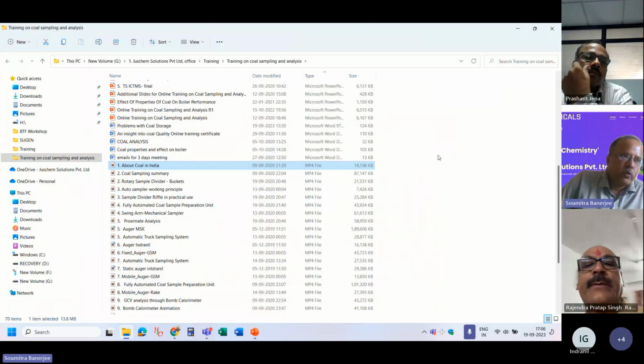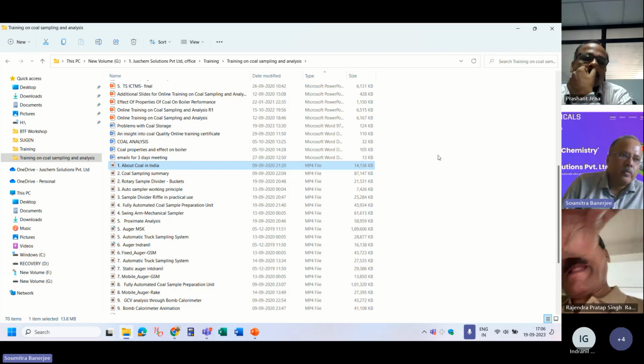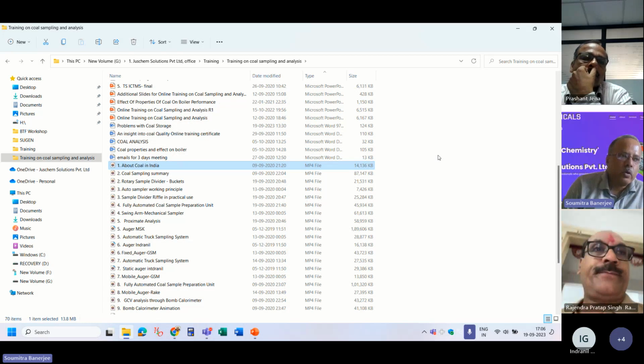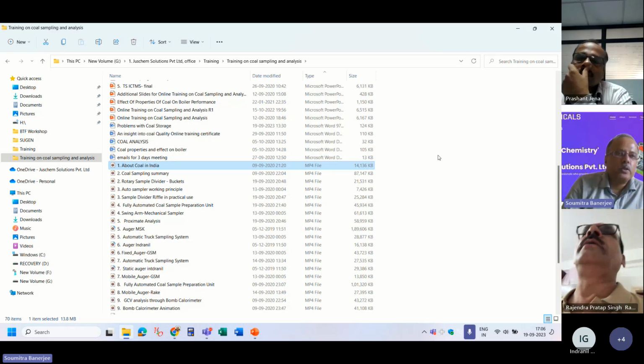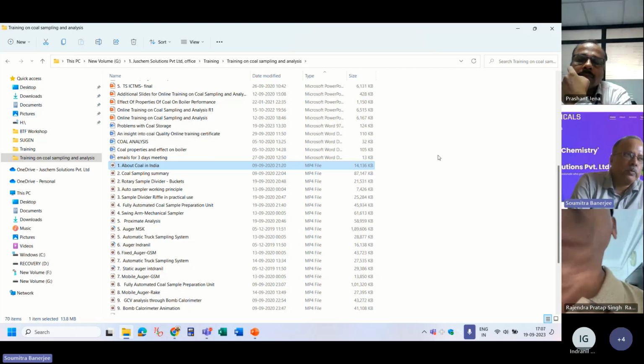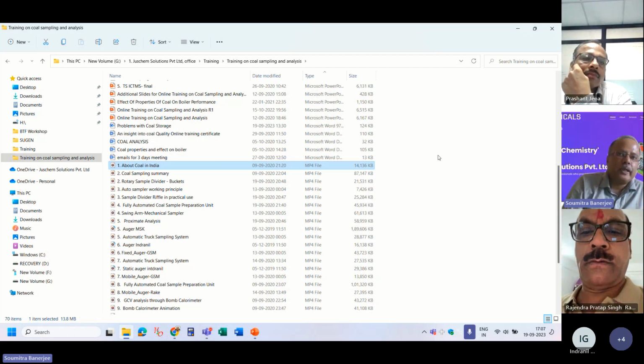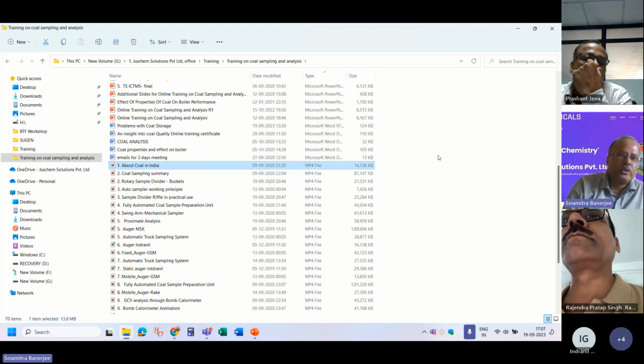Actually, if you do not do the sprinkling properly, then the spontaneous combustion actually increases due to the moisture percentage. The moisture goes into the voids, and later on, the oxygen goes into the voids after releasing the moisture, and then it increases the spontaneous combustibility of that pile if it is partially wetted. And second, if the surface moisture is increased and you are measuring through the right standard and right method, nothing is going to change.